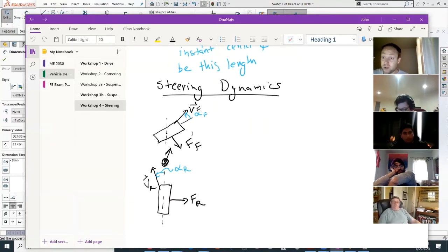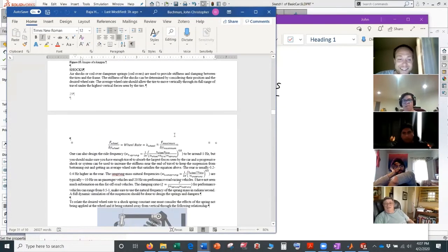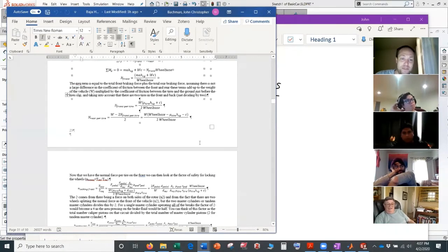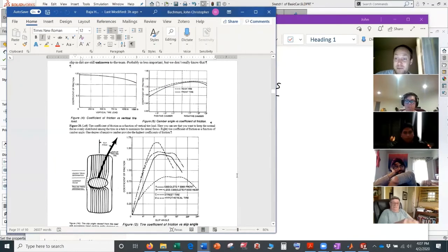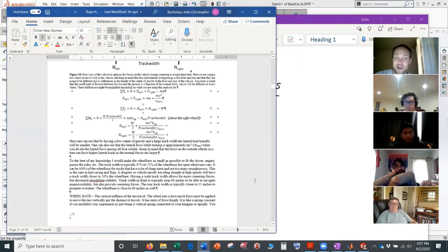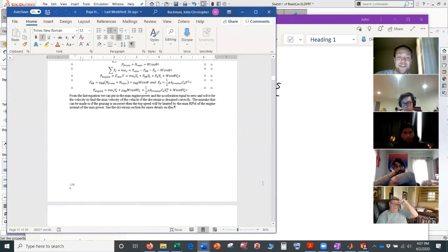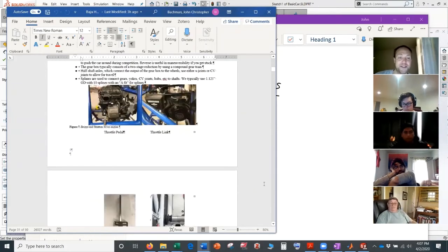Okay, so remember that in the elastic regime of the tire, you guys are gonna kill me. So what do I mean by the elastic regime? You've heard of elastic and plastic deformation for materials. You've seen where there's a linear relationship between stress and strain, and you call that the elastic region. We do the same thing for tires.